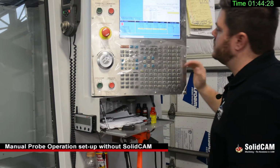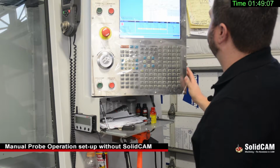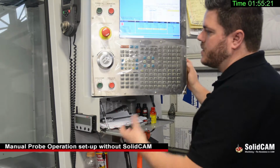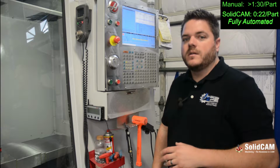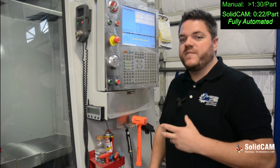And then we're going to record the Z using a single surface. So now we're just going to go back here. We're going to do a single surface. Come over. We're only going to travel in the Z distance. So I will tell it to go roughly 200 thou, and then we'll go cycle start. So now that we showed you how to manually operate the probe on the machine, we have our SolidCAM program loaded in, and we're going to show how much faster it is.